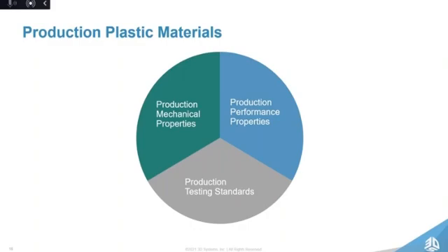end result. So in order to ensure we can compete against traditional thermoplastics, which is really the basis of what we're talking about here, we've really strived to ensure that our material data sheets carry the most comprehensive data that is relevant to the envisaged application areas. Importantly for automotive, that's carrying out the reported and proven accelerated aging testing, both indoor and outdoor, showing retention of mechanical integrity with exposure to common fluids and chemicals, and showing mechanical isotropy.